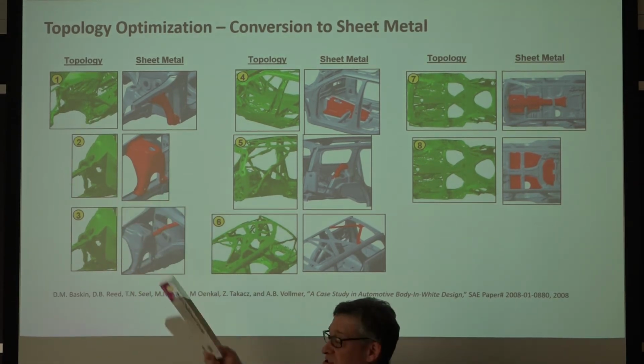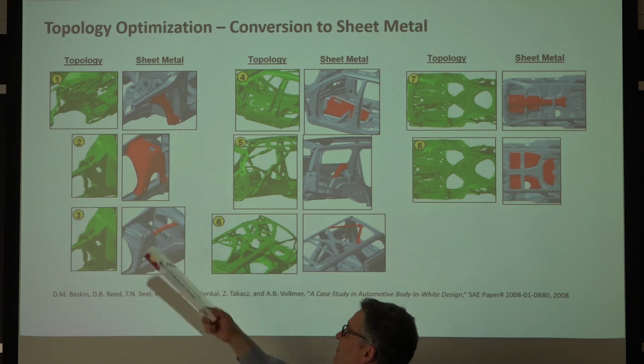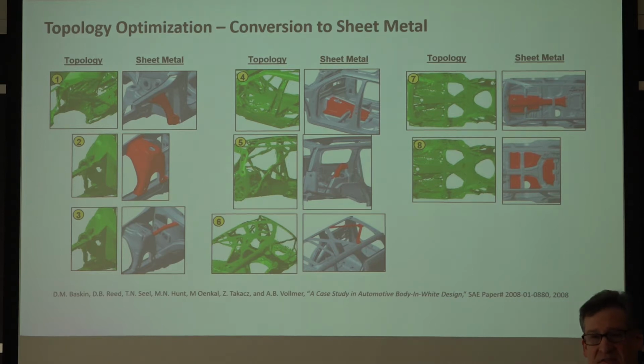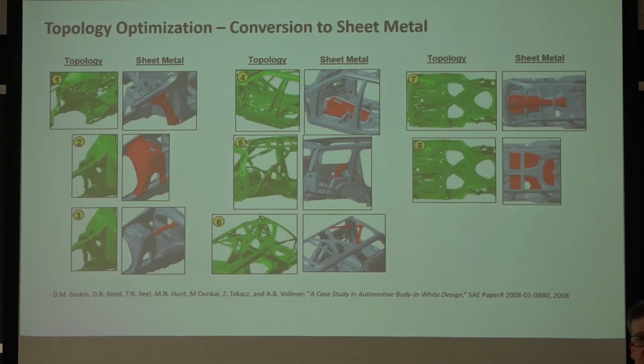The shock tower, we talked about that, about opening up a space in the middle because apparently the stresses aren't that high. Some of you who are car enthusiasts have probably seen these strut tower braces. Anyone into cars? A lot of tuners, a lot of people who spend a lot of money making their street cars faster, will put in these braces that might go from shock tower to shock tower, and we actually saw those types of load paths in the topology optimization result.